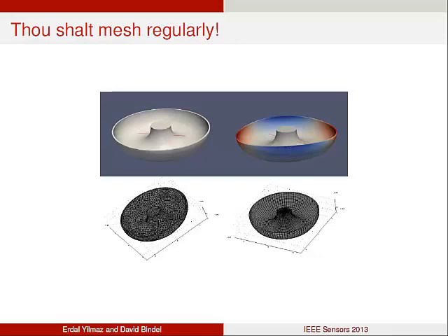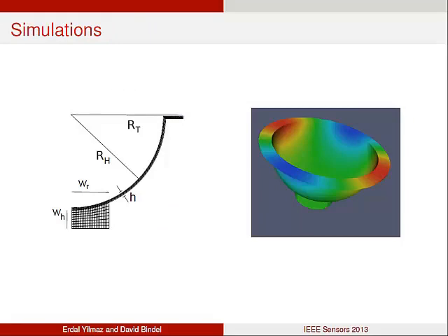If you want to consider imperfections on this geometry, then you would have to deform this structured mesh. And when you are deforming it, you again might end up introducing these spurious splittings. So in our simulations, we exploited the axisymmetry of the device and just worked on the cross section, which allowed us to use any element type on the cross section.